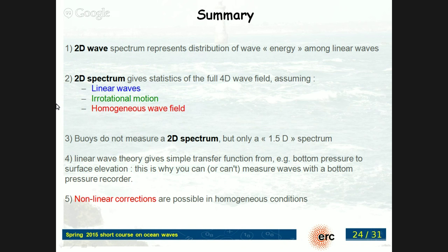Yeah, the linear wave theory gives you a simple transfer function from something like elevation to bottom pressure, or the velocities to the surface elevation. And this is why you can or can't measure the waves with a bottom pressure recorder. But again, if you're only interested in sediment properties, you don't need to go from the bottom pressure to the surface and then back to the bottom. Just stay at the bottom and transform the bottom pressure to the bottom velocity, and then you have a very good transfer function. And finally, yes, it's possible to compute some nonlinear corrections to this linear world.